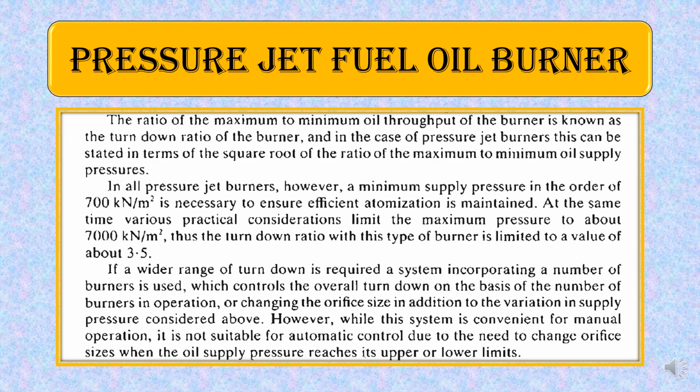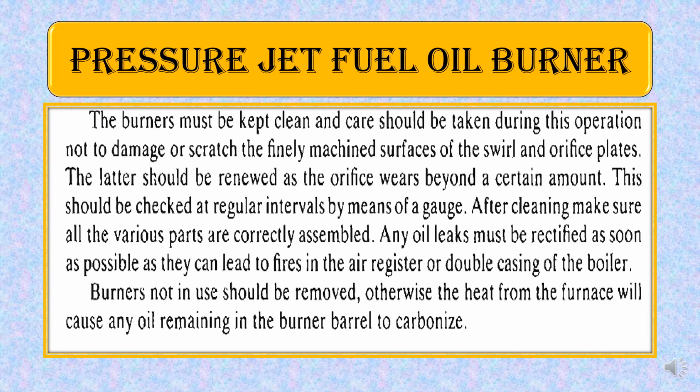Another method is changing the orifice size, in addition to the variation in the supply pressure considered above. However, while this system is convenient for manual operation, it is not suitable for automatic control due to the need to change orifice sizes when the oil supply pressure reaches the upper or lower limits. So this is the description of it.